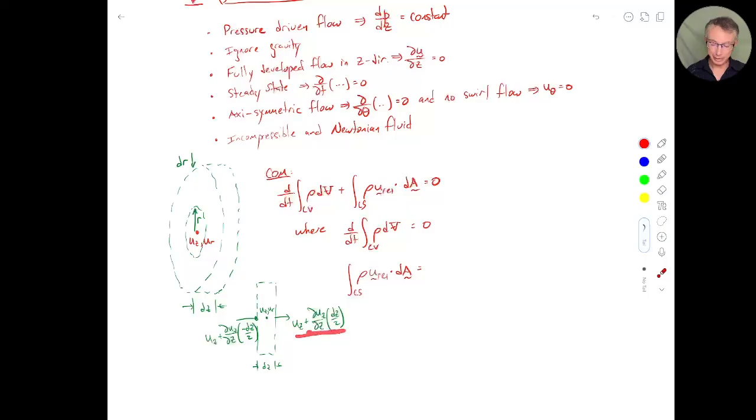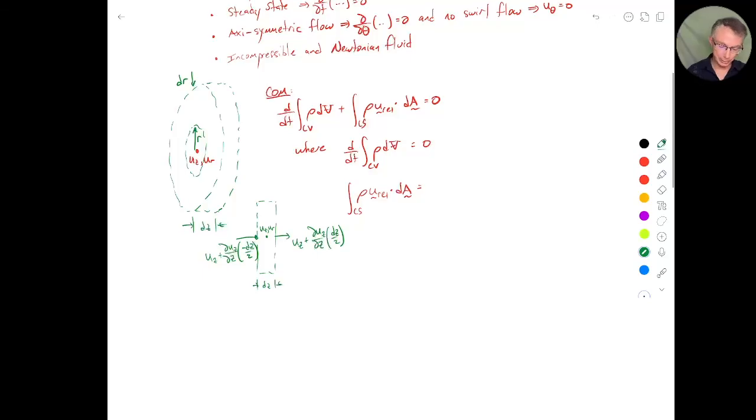The right-hand side, it's much the same. It's the velocity I start with, plus how the z velocity changes as I move in the z direction, times how far I've moved to go from the center to the right side. And that's a distance of positive dz over 2. Okay, hopefully you understand that. Now in the r direction, you might know just in advance that there's no flow in the radial direction in this geometry, and that's okay. But I'm going to pretend I don't know that yet.